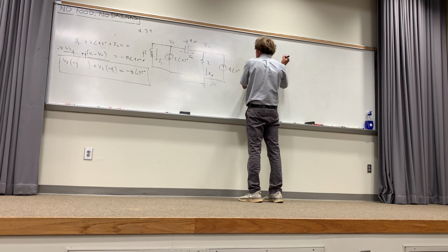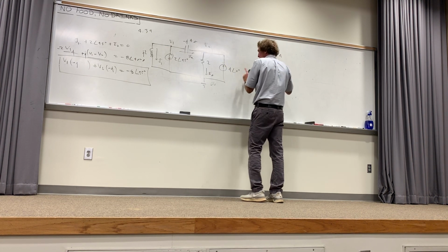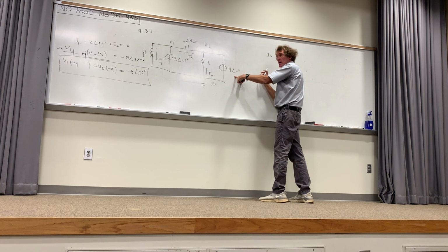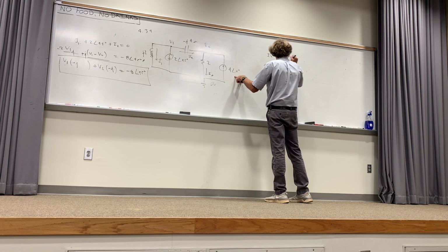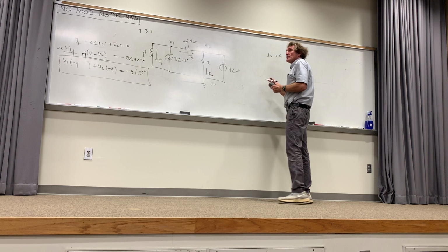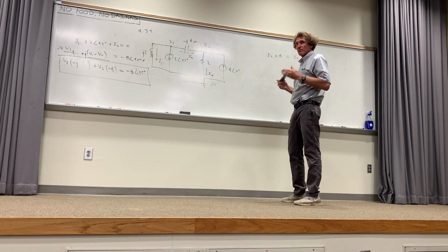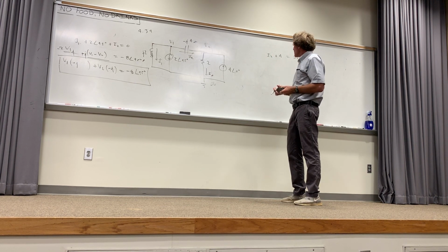I2, right, plus 4. Agreed? Because 4 is flowing in, right? How much is flowing out? Just I naught. If you get used to doing it this way, you won't make mistakes. What flows in, flows out. Now put in the voltages.